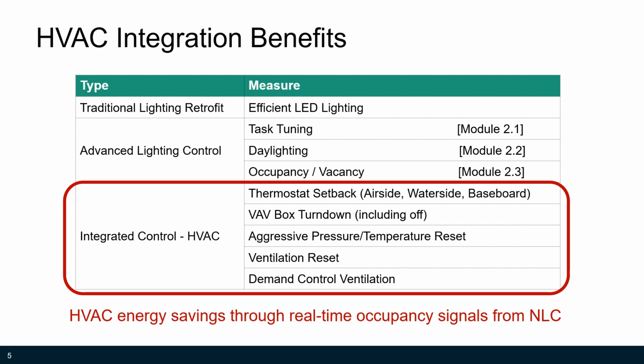In the case of variable air volume, known as VAV systems, additional strategies can be incorporated pursuant to ASHRAE Guideline 36 to control airflow. VAV box turndown or shutoff reduces or shuts down airflow when an unoccupied signal persists for 5 minutes. Similarly, an AHU RTU supply fan can be set to a minimum speed or shut down in the case of an unanticipated, unoccupied status.